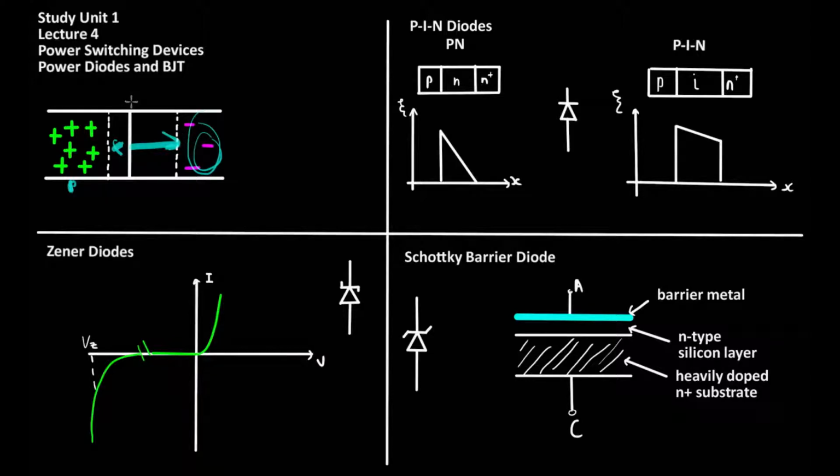A good way to circumvent this problem is to make the p-n junction much wider than would normally be required. So what would happen is the diode would have a very wide p-n junction over here. Another advantage of using very wide junctions is that the thermal performance of the diode is also improved.